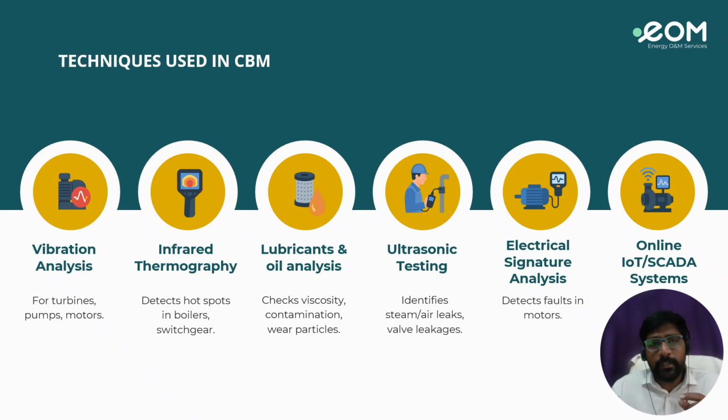And the next one is lubrication and oil analysis. It examines lubricants for contamination, viscosity, and wear particles, providing insights into the health of the gearbox, turbines, and hydraulic systems. And the next one is ultrasonic testing. It captures high frequency sounds which are undetectable by the human ear, useful for detecting steam leaks, compressed air leaks, valve issues, or electrical discharges as well.